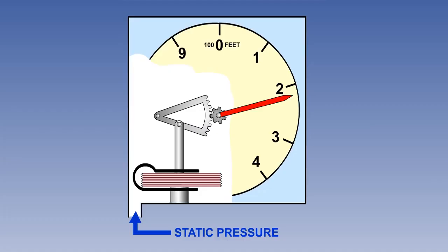Let's look at how the altimeter works then. In its simplest form, static pressure is fed into a sealed instrument case from the static source. Inside the instrument case is a partially evacuated capsule, or aneroid capsule. Expansion and contraction of the capsule is kept under control by a leaf spring, and the controlled movement is transmitted via a system of linkages to the pointer on the instrument dial.